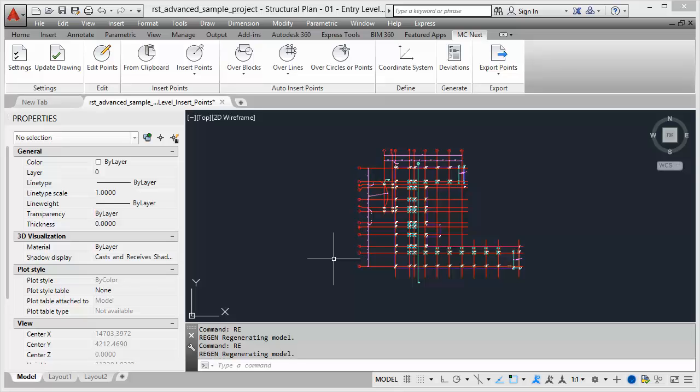To position the drawing to the real world survey point in the field, we're going to use the define coordinate system wizard in CAD. To do so, we're going to use two reference points that are measured by the surveyor in the field, and make these two reference points present in the CAD drawing, so we can snap to these points. In this example, we're going to use the two corners of the building here.